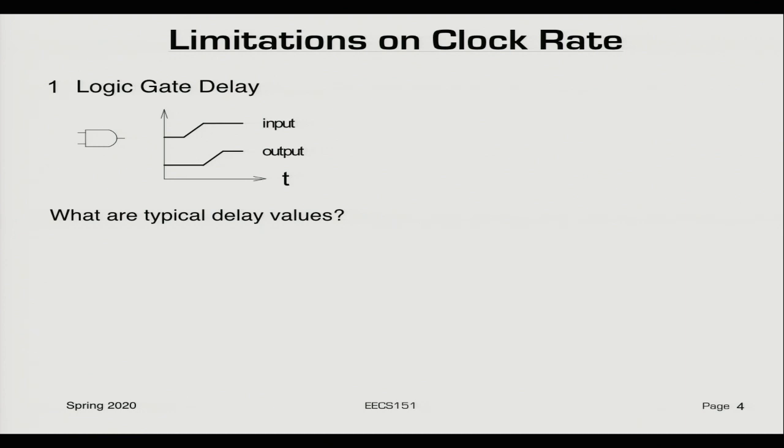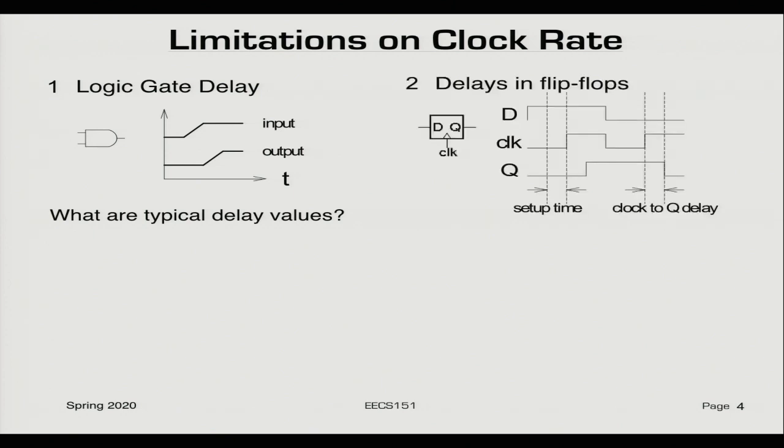So you can guess that logic delay has to be somewhere in the range of a tenth of a nanosecond or tens of picoseconds, right? Okay. So I'll tell you what it is in a minute. But, okay, the other place we get delay is in flip-flops, right?